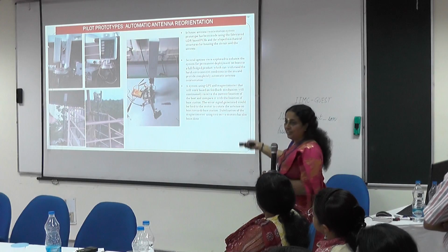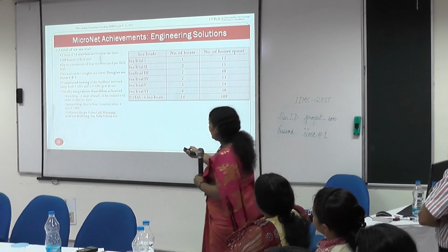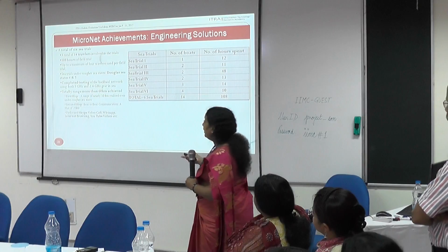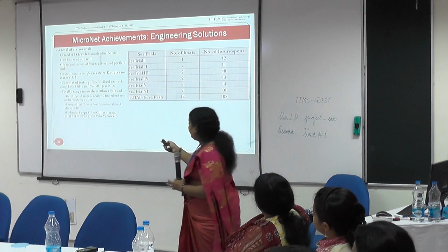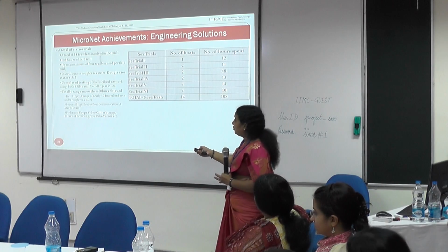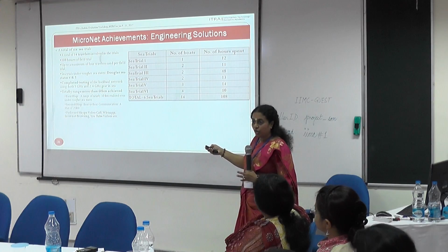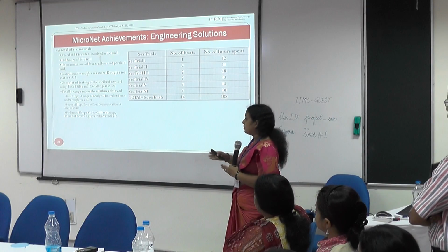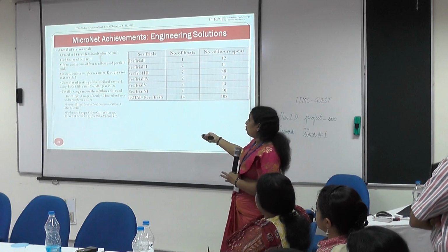I'm not going into detail on how we have implemented all that. As of now, we have done 6 sea trials with 14 trawlers, where we have spent almost 108 hours at sea. This is what the 6 sea trials look like. Up to Douglas Sea State 4 to 5, we completed testing with 5 GHz and 2.5 GHz. A maximum range of more than 60 km has been achieved, where the first hop is nearly 50 km. The second hop, which is the board-to-board communication, is a maximum of 20 km, and performs Skype call, video call, WhatsApp, internet browsing, YouTube, etc.